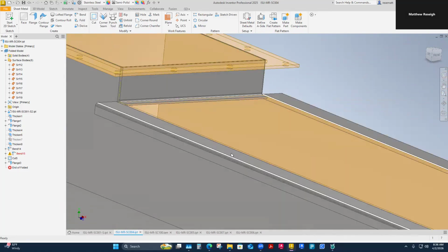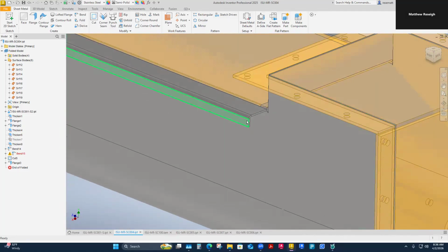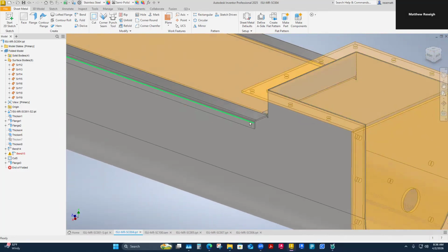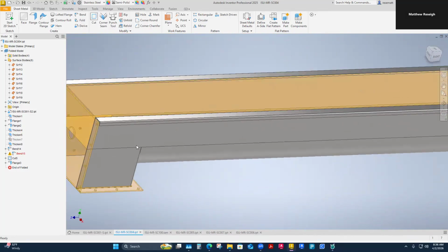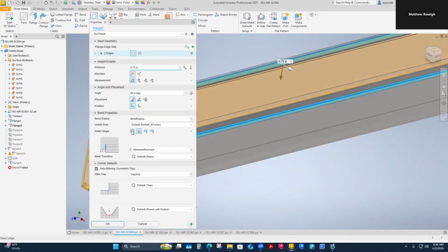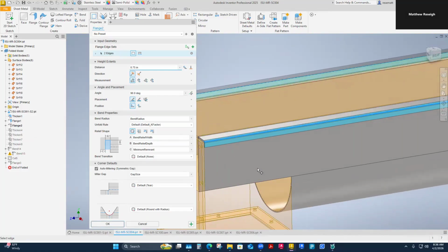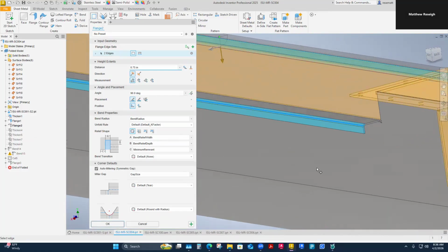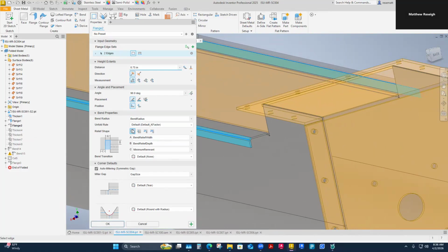The other thing I'm going to do is fix that on the other flange too, even though it isn't necessarily impacted by that, this outer flange. I'm just going to think consistently. If I made that change to this flange, I'm going to make that change to this flange as well. So I'm going to edit its feature and run it by default settings here too, which won't impact that at all. It doesn't have any of those features to relief cut for, but I'm just going to keep things organized. I do that a lot.